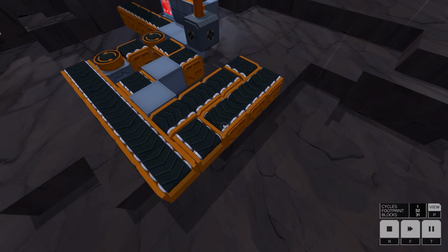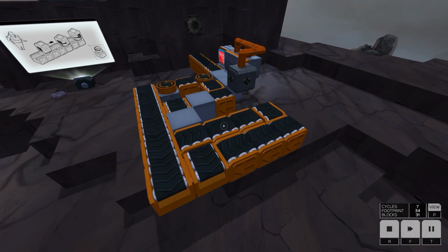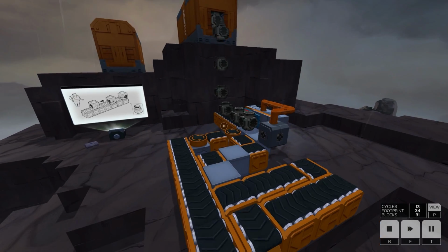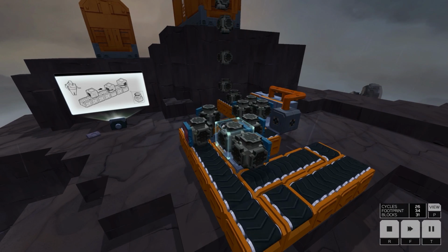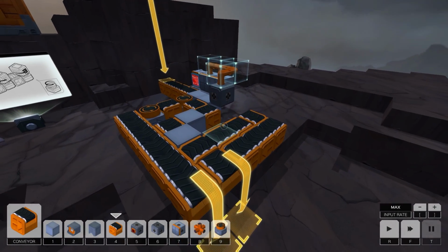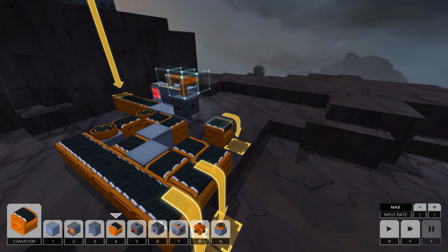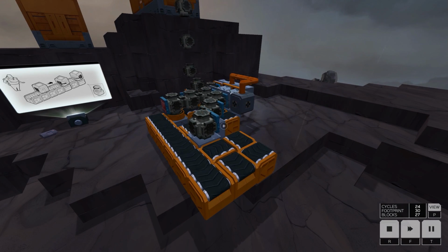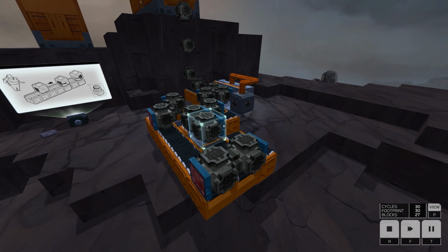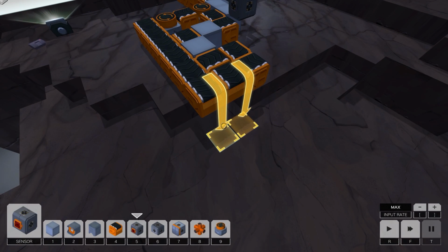And then we should be able to hopefully adjust that for the time we need to delay it long enough for the 2 rotation pieces. Stall there. See, the rotator stalls, but then it also takes a bit of time. That's way too far. Okay, let's try just this. Let's just fast forward a little bit. Yeah, okay. Stall. Push. Yeah, see, perfect. Okay, so now they're in sync.